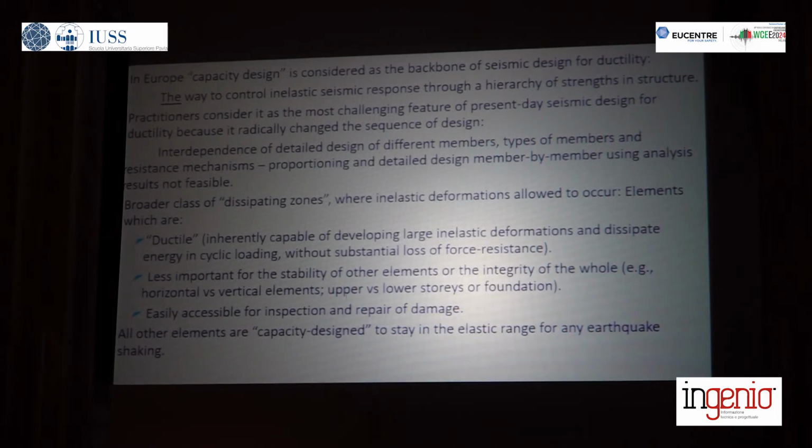For example, the horizontal elements are considered less important in that respect compared to the vertical. The elements near the top of the structure are considered less important for the whole than the foundation. And also the regions which we choose to have the inelasticity and the ductility demand concentrated should be accessible for inspection and repair in case of an earthquake.